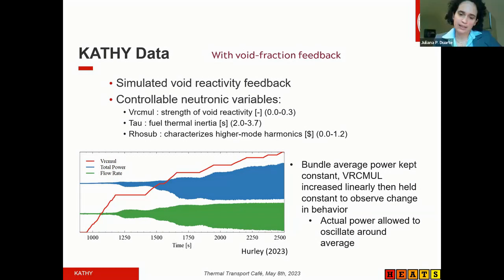But one thing, if I can add, is that all of these transition boiling and post-critical heat flux models that we have nowadays still have a very large uncertainty, and we still don't include effects of surface on those models. Exactly. Okay, thank you.